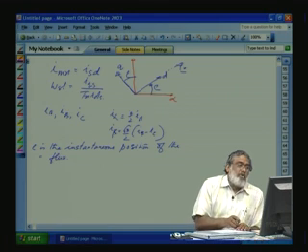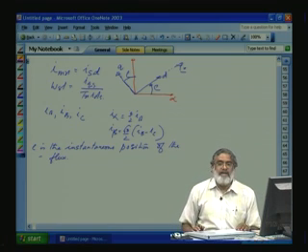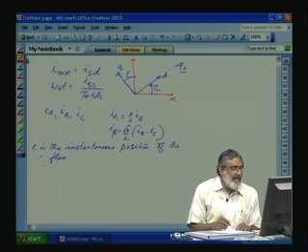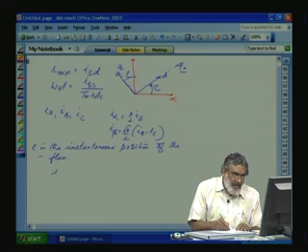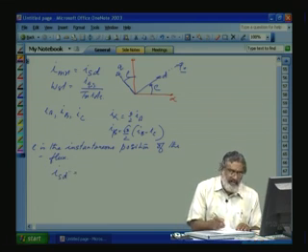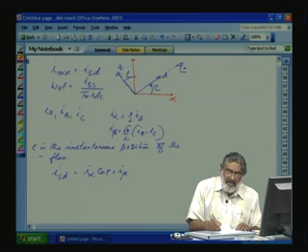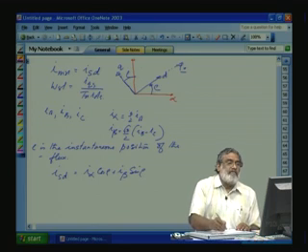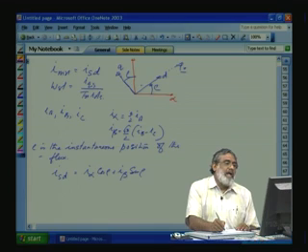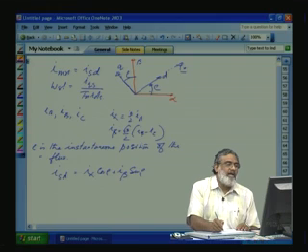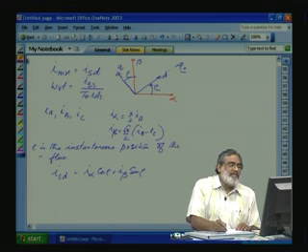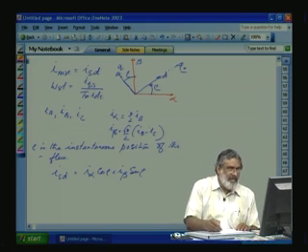Of the rotor flux. So, now for field orientation, we have to find out the ISD and ISQ. Now our ISD is equal to I alpha cos rho plus I beta sin rho. From this figure, I beta sin rho, this is the beta axis. I beta sin rho, that perpendicular, is this axis. This is our I alpha from here.